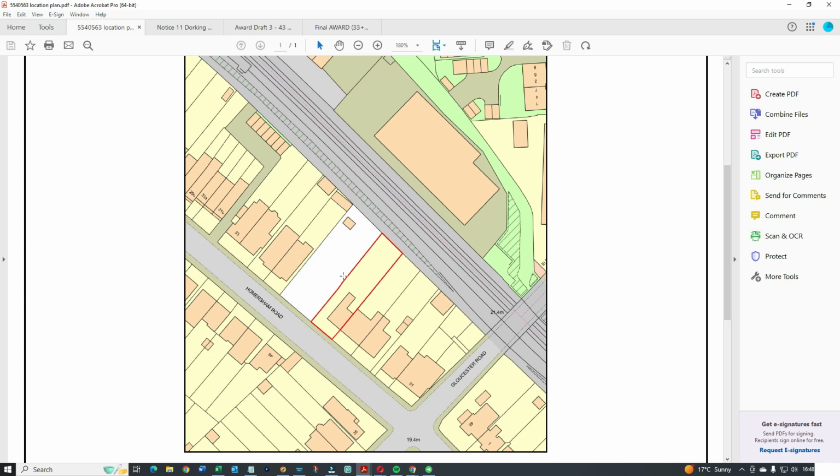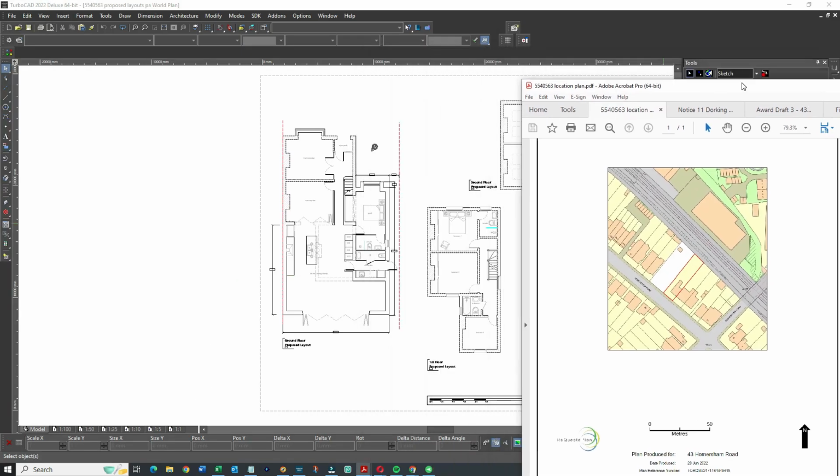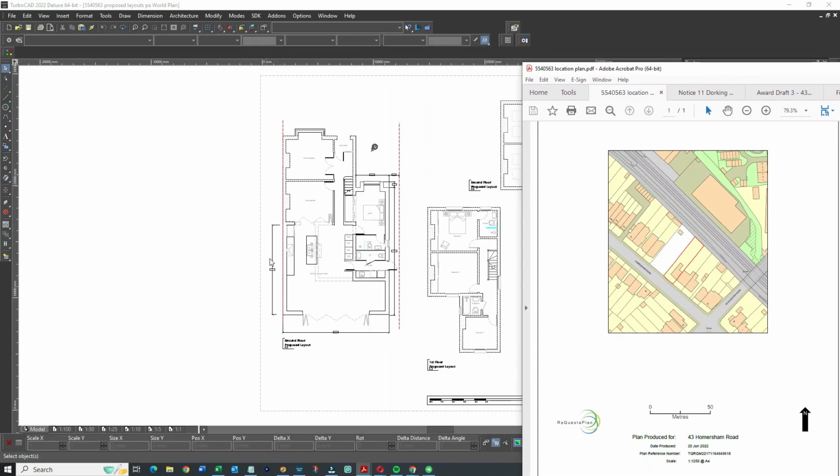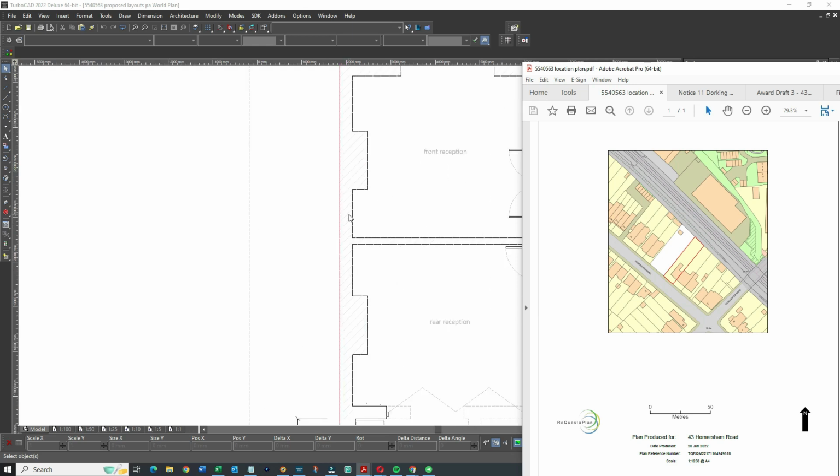So now you've seen me discuss why, and I'm going to sum up a little. You've seen me discuss the kind of project where you would need a party wall surveyor, or a party wall agreement. I was explaining, as in excavating or carrying out structural works within 3 meters on the excavation, and structural works that will have an effect on or be part of the party wall. Like if you were putting in this bit of steel here, that's going into the party wall, and it's got to sit on a lintel or another bit of steel or on a plate. That means you're cutting a section out of this party wall. That means a party wall agreement.